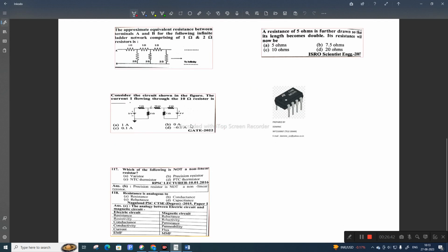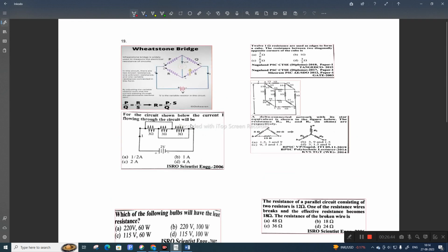Some of the MCQ questions which I have given for you here, and one more concept is there, the Wheatstone bridge. The Wheatstone bridge is very useful to find an unknown resistor. You connect this type of bridge form and vary this resistor, so that the galvanometer current will be 0. By this null method you find the unknown value of a resistor. This is the basic principle.